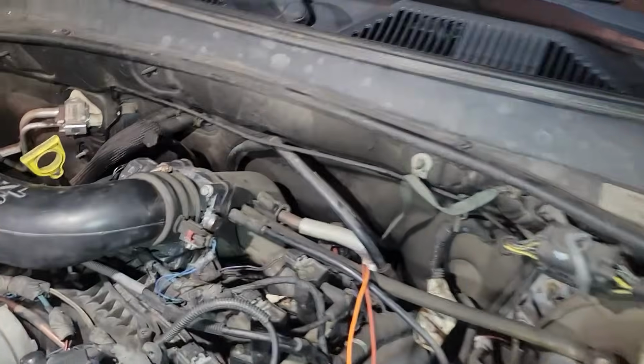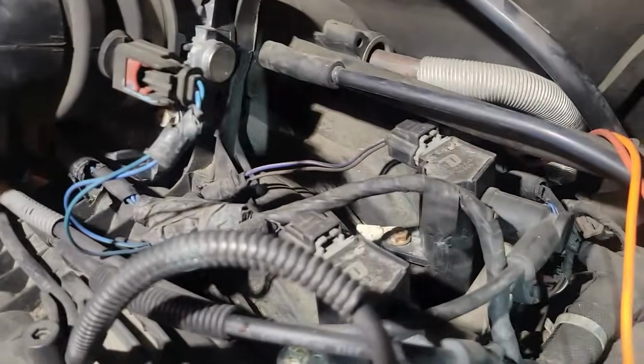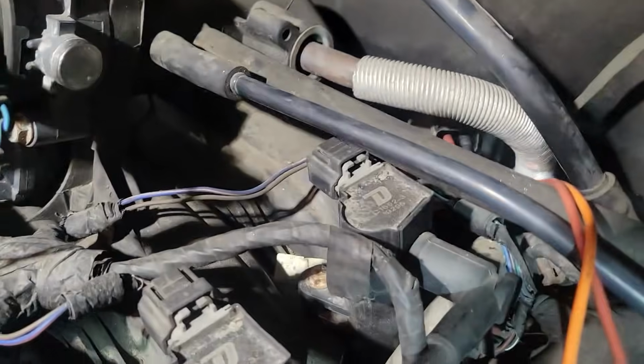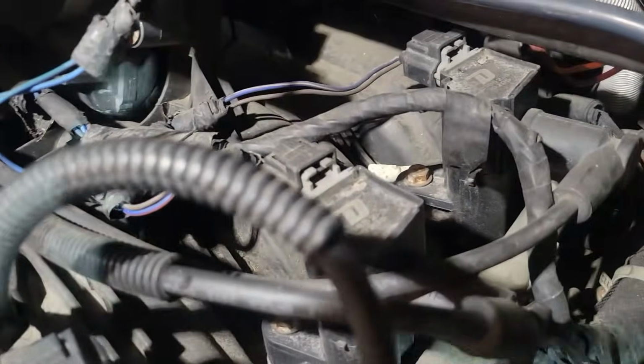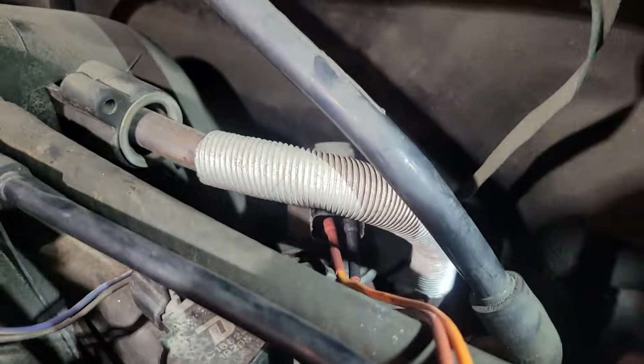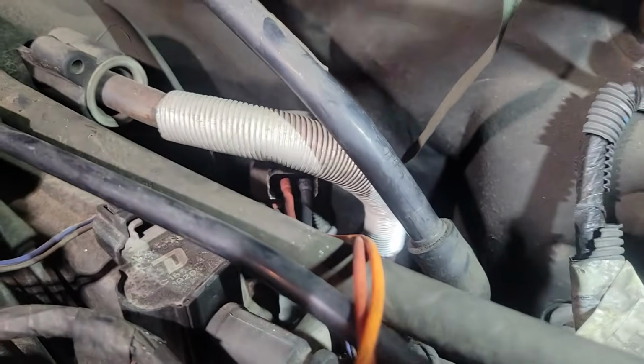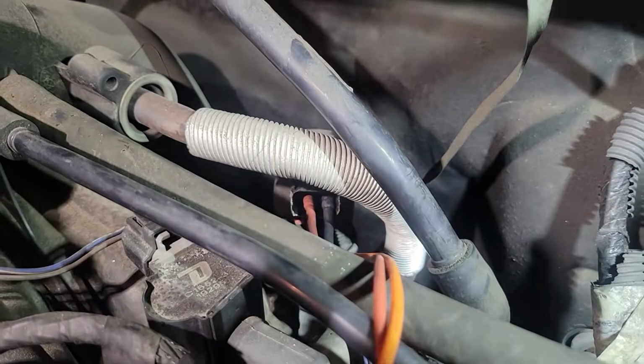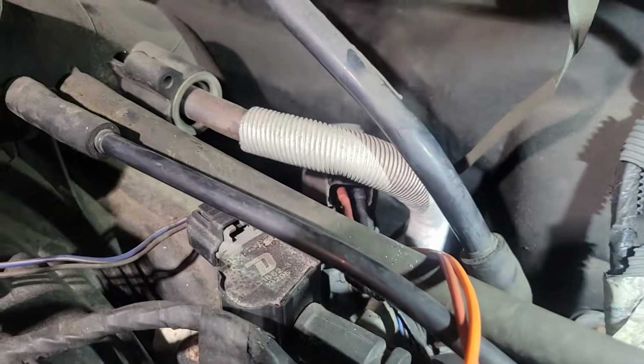All right, the resistance on the EGR valve. I never trust these on Dodges, or a lot of times on anything really. A lot of times they stick open. I'm just trying to figure out why this is taking away so much fuel at idle. We're above 10%, so that's when you really start looking for a problem.